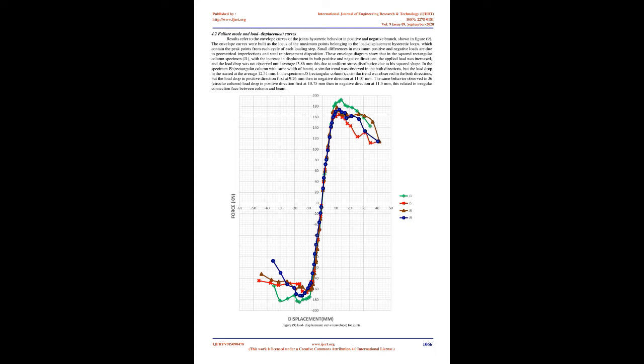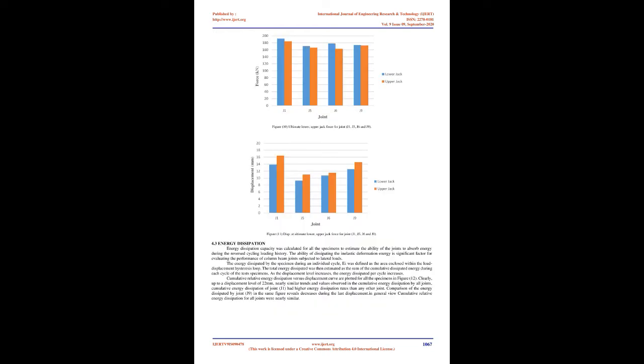Although all the column sections have the same moment of inertia, the squared section column of joint J1 has higher capacity to resist load and moment than other sections, and the rectangular section of J5 was the lowest capacity one. This is related to the section dimensions, the area and position of steel. For all joints, the point of load and moment due to the displacement at the edge of the beam was at the interaction diagram curve of each column section, near the balanced failure point.